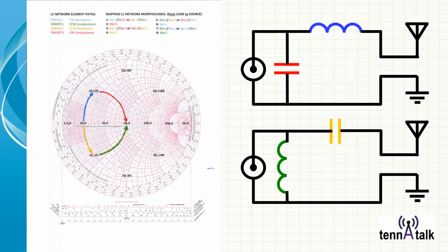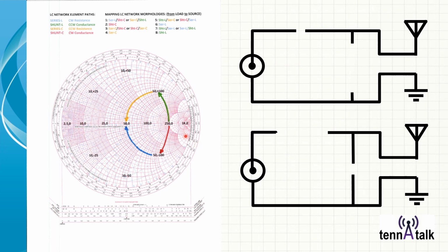So let's look at a different configuration now. I'm starting from a high pure resistance, no reactance, and I use a shunt L to go counterclockwise on a conductance curve, until I get to a nice 50 ohm resistance curve right up here. And then I navigate down towards my 50 ohm perfect resistance with a series C. Likewise, I could go the other direction with a shunt C going clockwise along a conductance blue circle, and then going clockwise on a resistance circle with a series L component.